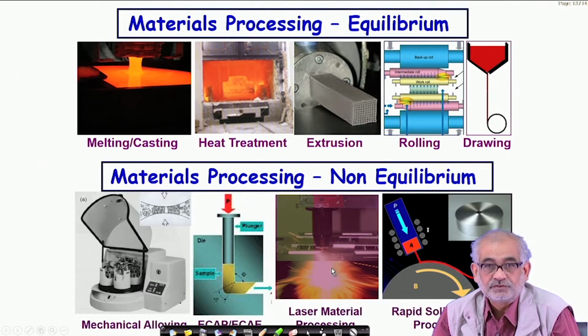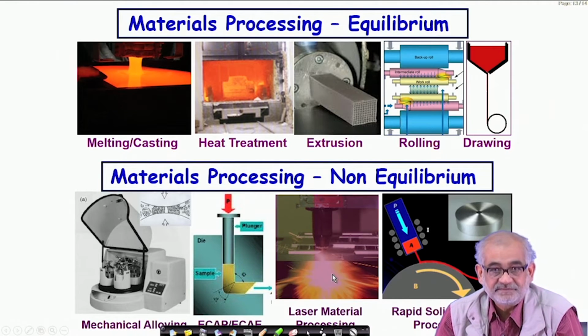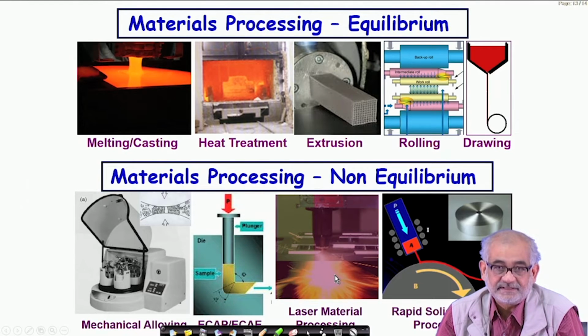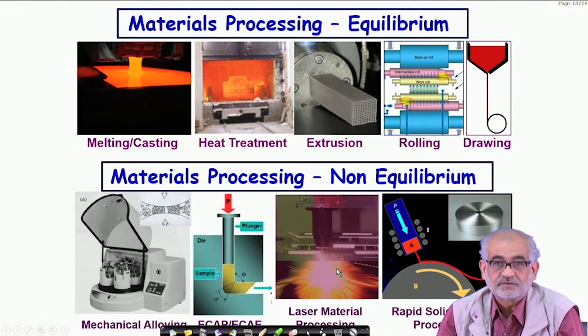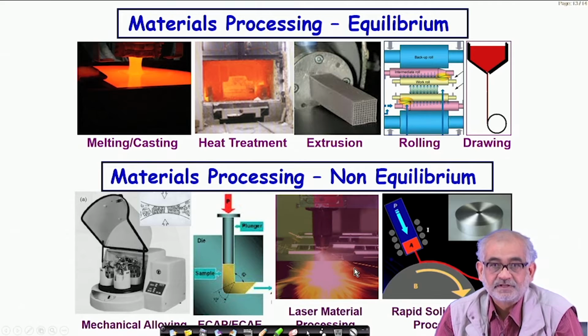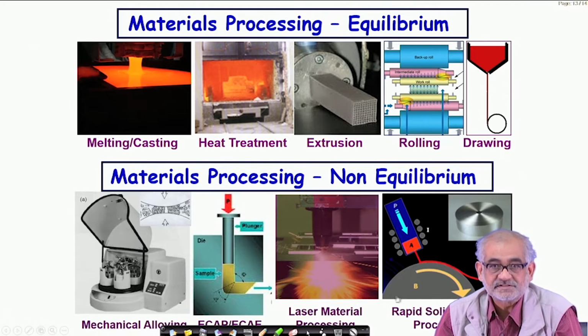We can do melting of a very small volume using a laser beam, and under the beam we can instantly take a solid in the form of either bulk solid or powders or wires into the liquid state and then subsequently quench them by self-quenching and create certain solid objects from small and gradually build into a bigger one through an additive process.